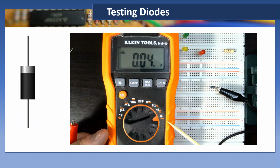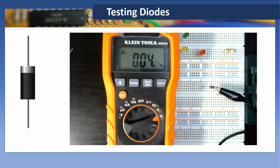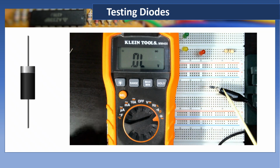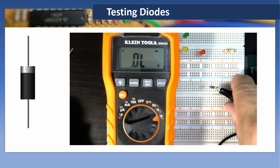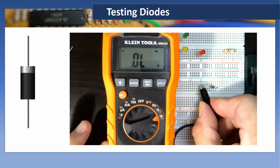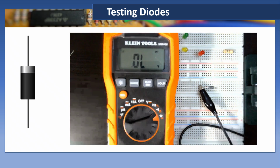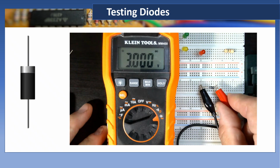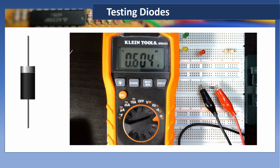Right now it's got an F, which is telling me that's farads, which is capacitance. So I'm going to press my select, and I've got the arrow hitting the wall symbol to tell me I'm on diodes. I have to watch my polarity. So the first thing I want to make sure is that I have my black lead connected to my cathode, and then I'm going to take my red lead and connect that to my anode, and I'm getting a little more than 6.6 volts.